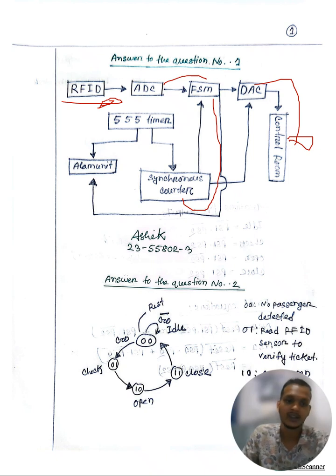the control room. At the same time, if the RFID sensor generates 4 pulses within a short time window, the alarm logic detects this and triggers the alarm. The FSM immediately closes the gate and stops further entry. If the counter reaches 10, the FSM will no longer send an open signal until the count decreases.